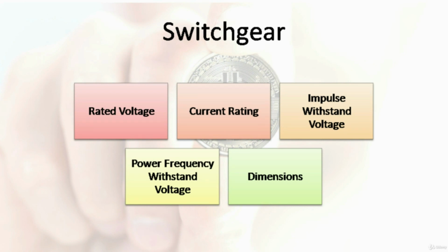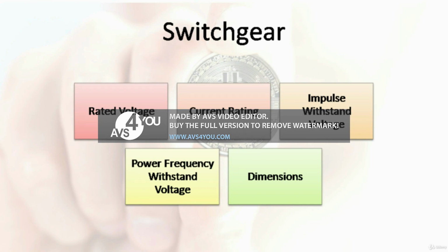That is the location at which the medium voltage feed is terminated within the facility. If you have a medium voltage generator, it would also be connected to this. It is also the duty of the medium voltage switchgear to disconnect faults and to monitor the medium voltage power delivery, for example, when isolating a section for purposes such as routine maintenance.